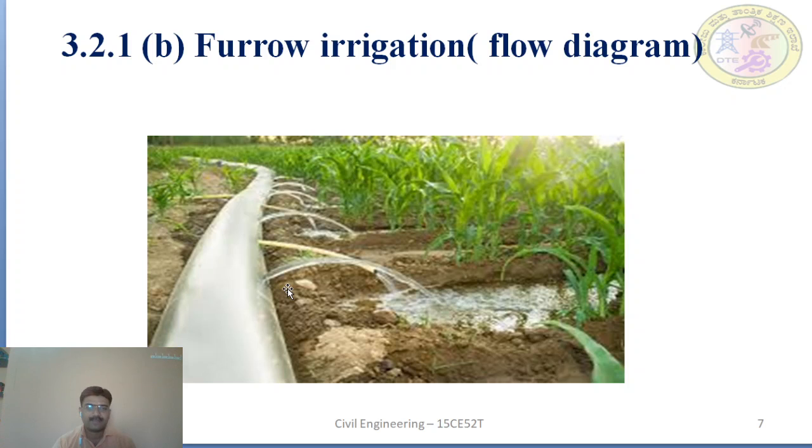Now, when the water is supplied through the supply channel with a certain pressure, this water will be discharging out through the pipes or the impregnated holes present on the circumference of the pipe. Now this water is falling on the rows, which are all parallelly placed, and the whole surface gets wetted. The most important concept to be noted here is that it must have a uniform slope. If the slope is not provided, the water will not flow to the further length.